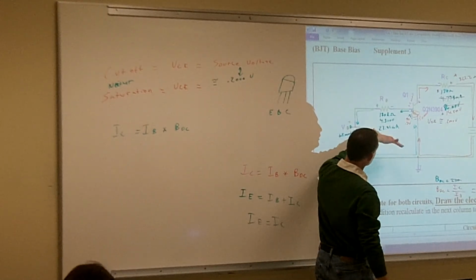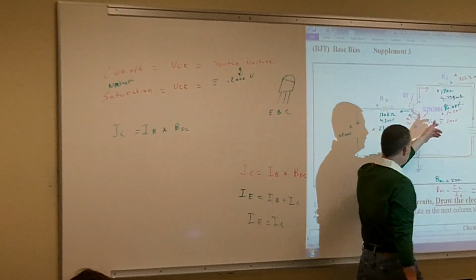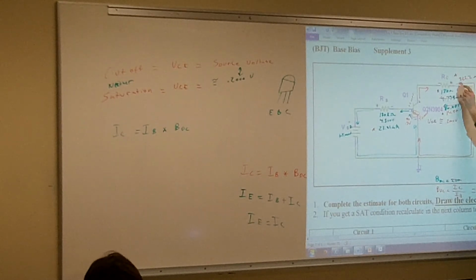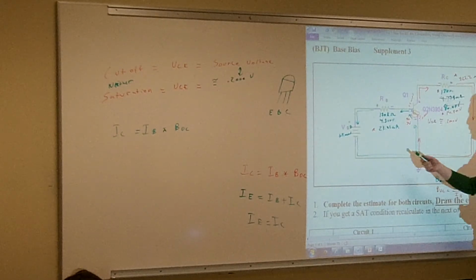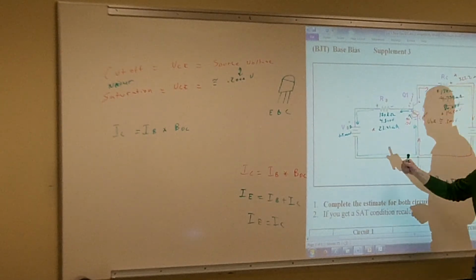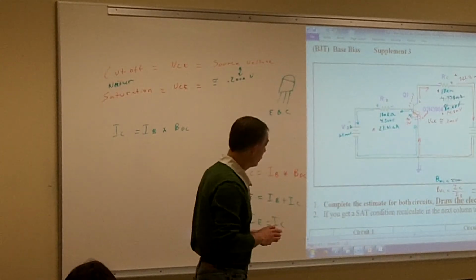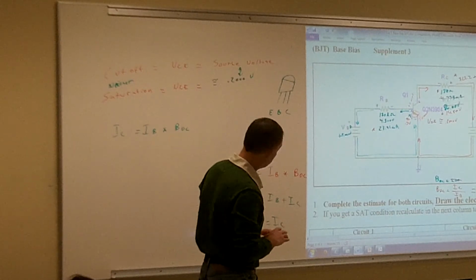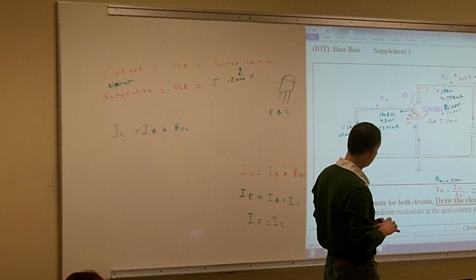Yep, the two separate circuits, but you can see that we can get some gain. So this circuit would actually work like a switch. I could put an LED right here, and put a current limiting resistor in there, and my LED would light up with just a small amount of current. We're going to take a look at transistors as switches later on after we get through all this. We've got some worksheets for transistors as switches and also for LED drivers.